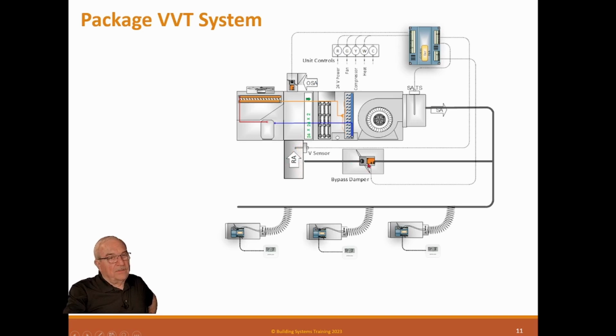And so these can take all the air they need, and this will sense it by the velocity changing, and it will change the damper position. These actually work pretty well. So you can dial this in really good. And of course, other than that, it's a standard VAV, except these boxes down here. This unit has a little bit of a problem, and that is that this is a package unit, so it's got heating. Well, this happens to be a heat pump, but it could cool or it could heat.